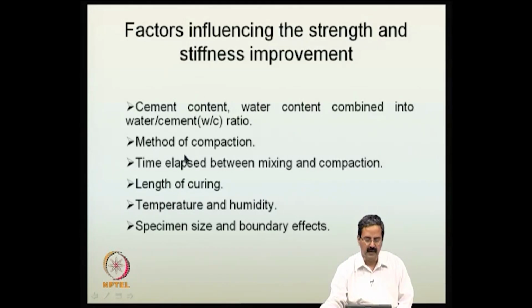Then the method of compaction. There are different methods of compaction, whether it is shallow or deep, and that is an important factor, because essentially we need to have the proper equipment for the compaction. The other important point is the time elapsed between mixing and compaction.